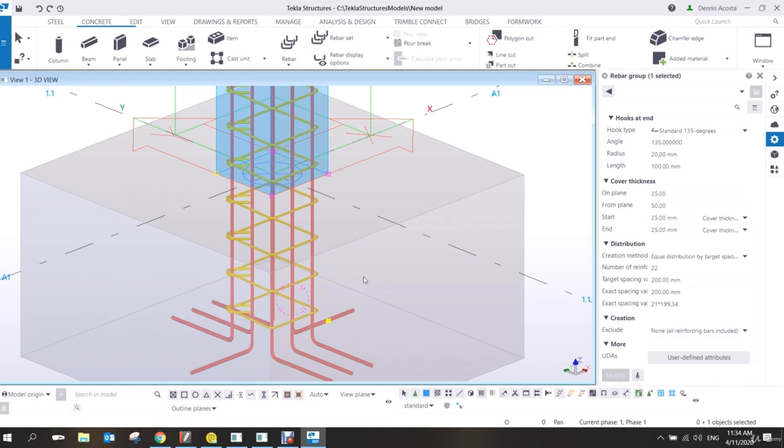So you need to be careful on the position of the reinforcement here, because we have already 3, so meaning you need to have something like, let's say, 4 rebar here. 1, 2, 3, 4. 1, 2, 3, 4. Okay? So 4 rebar on the beam. Alright, so that will be our exercise before lunch.